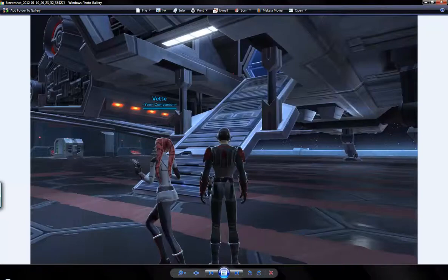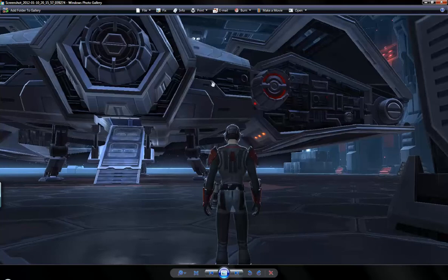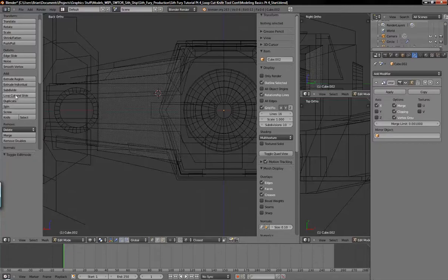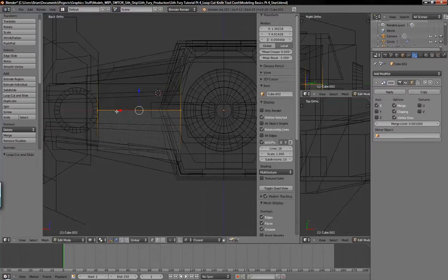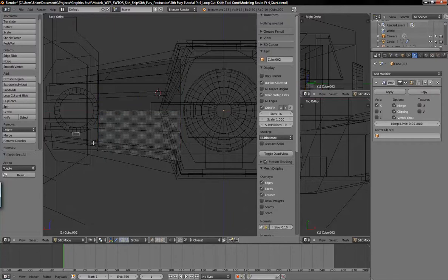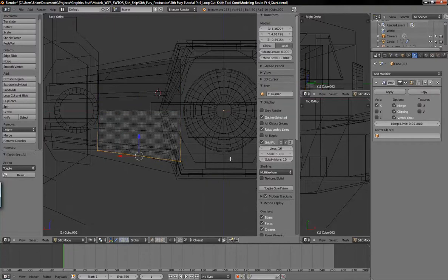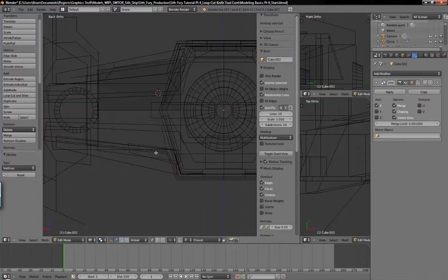And since we have a symmetrical piece, we can cut off the bottom half here. So just loop cut this middle. Loop cut right there in the center, and A, deselect all that. B, border select this, and we will delete these vertices.